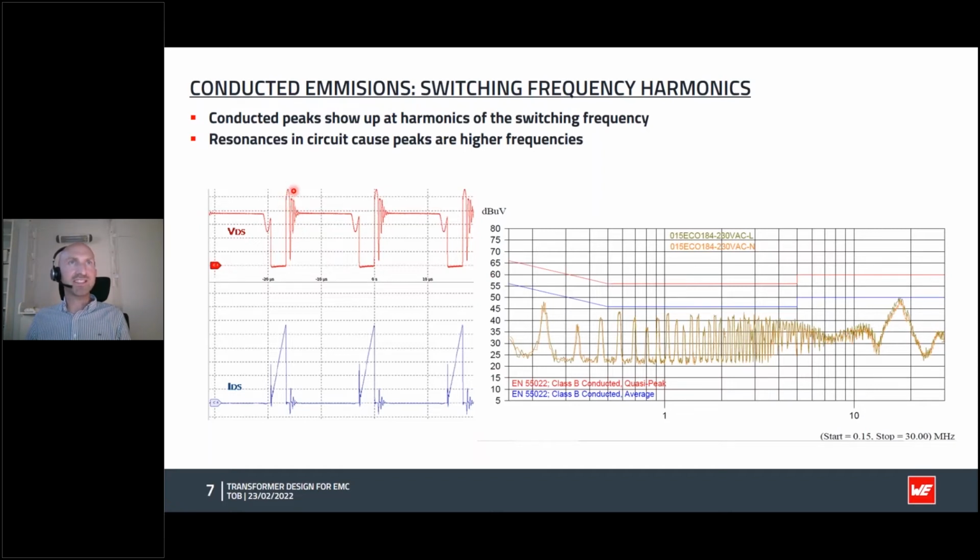So we typically have to dampen this, or this voltage spike can go extremely high, and we dampen that with a snubber circuit. You can use resistor capacitors, or resistor capacitor diodes, or even Zener diodes to dampen this, but it all eats into your efficiency. So if we can reduce leakage, we can increase the efficiency of our power supply. Then, yeah, that's the voltage side of it.